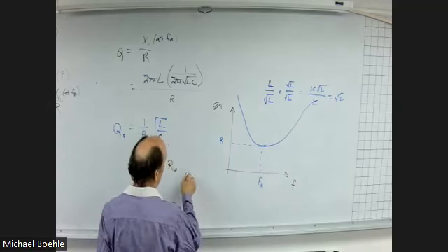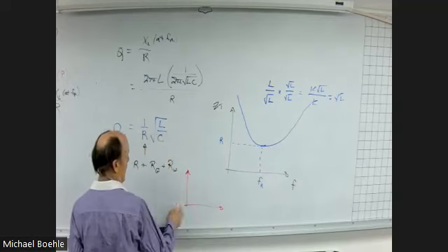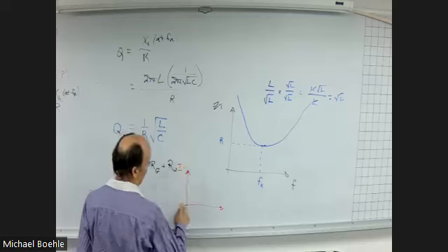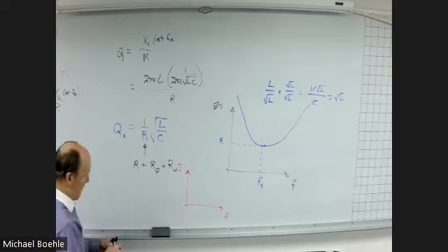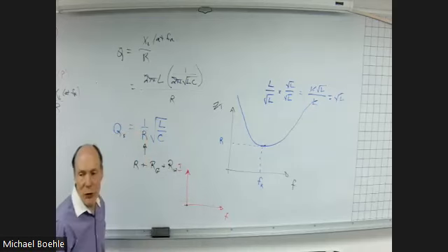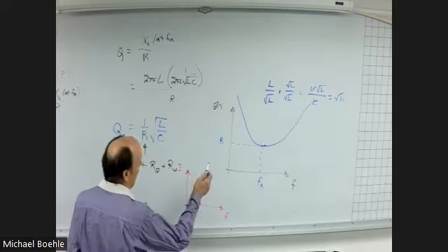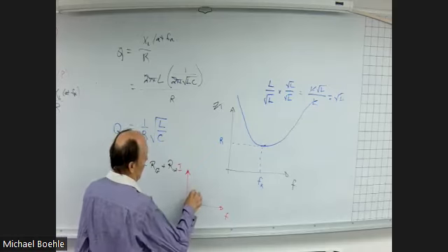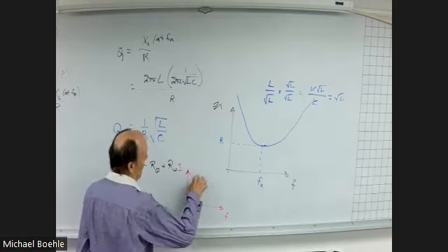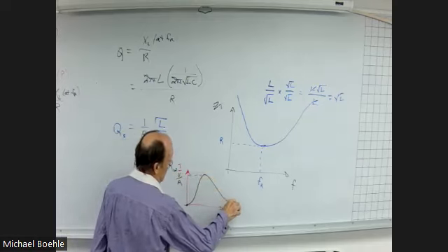If I were to graph my current in the circuit versus frequency, if I wanted to say zero, I could just say, well, zero frequency is DC, you have no current. But then, of course, it's going to build. It's going to reach a maximum, which will just be V over R. And it will drop off.